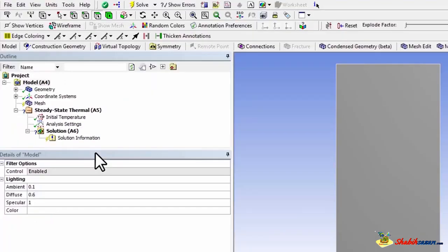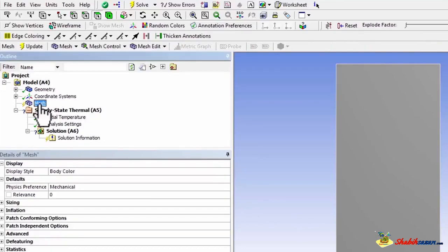After a little bit of hesitation, Ansys Mechanical comes up, so we can specify the mesh here, and we can also specify boundary conditions and so on. So let's highlight mesh. And I usually like to throw a default mesh on it. Sometimes it doesn't work for very complex geometries, but usually it works. And then tweak that default mesh to get a more suitable mesh.